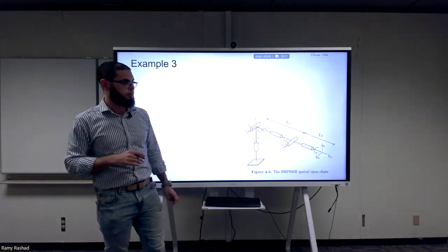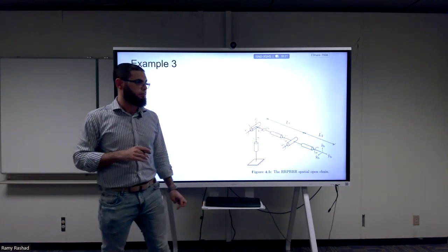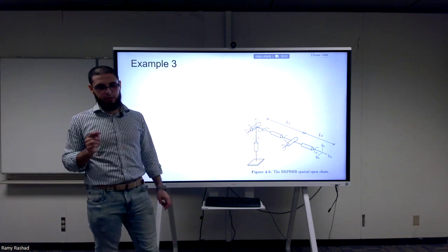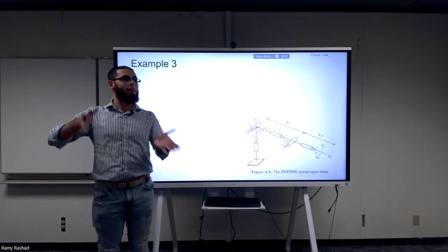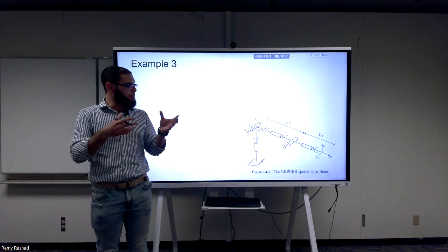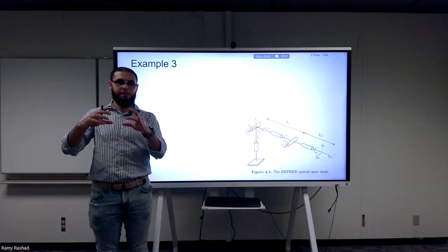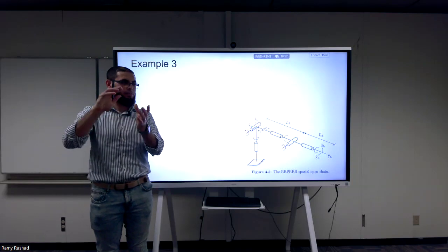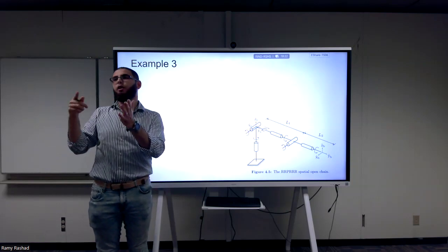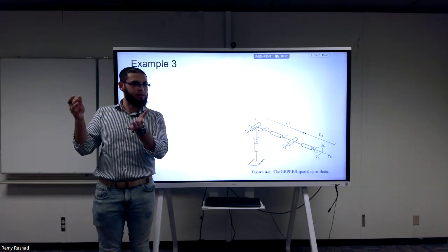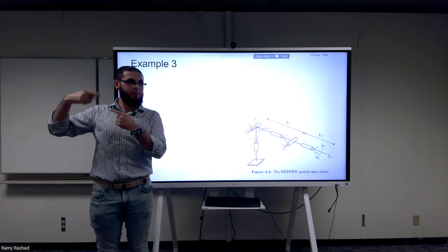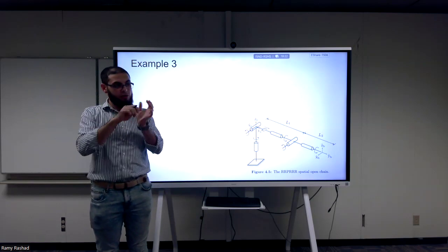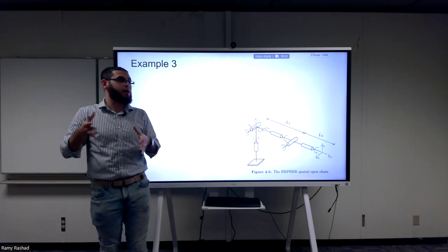Does that imply that if I'm using the robot over and over again, I have to calibrate the home configuration? The home configuration, okay, that's a good point. You have to go back to it in some sense. This is an implementation issue. If you're using, for example, joints with sensors or encoders, and you're using incremental encoders, you don't have a home position in an incremental encoder. So you need to define in some way in the robot itself where the home position is.